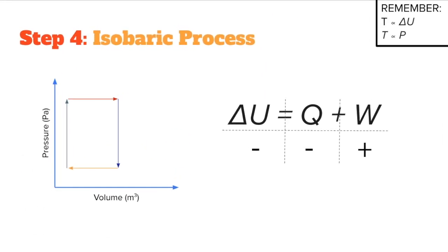The fourth and final process that occurs in the can is isobaric, with the volume of the can decreasing. This can also be viewed as a horizontal line on the P versus V graph. During this final step, the boat pops for the second time. Cold water will rush into the engine through the straws due to the difference of the high pressure in the water to the low pressure within the can, causing the shape of the can to return normal once again.